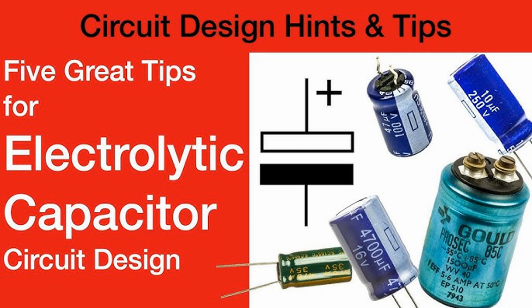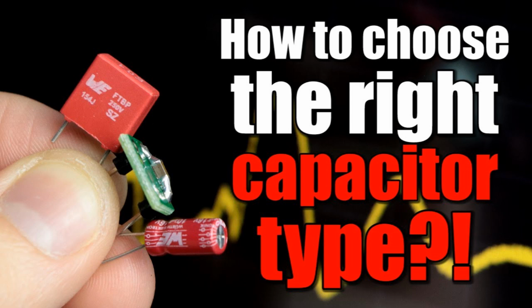Principle: frequency selection. Capacitors can be combined with inductors to create LC circuits, where the resonant frequency of the circuit is determined by the values of the inductance, L, and capacitance, C. The resonant frequency, f0, of an LC circuit is given by f0 = 1 / (2π√(LC)), where f0 is the resonant frequency, L is the inductance in henries, C is the capacitance in farads.